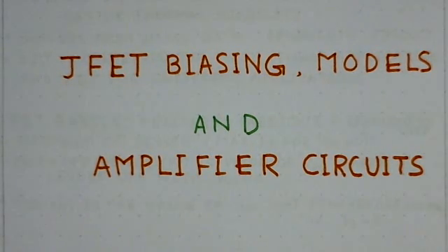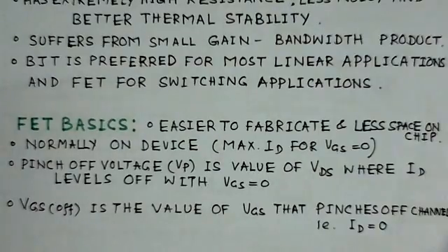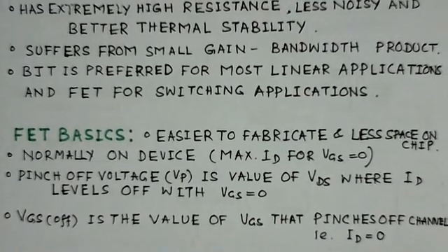A table gives various parameters for common source, common drain, and common gate configurations. Typical parameter values are compared for FETs and BJTs. BJT common emitter and common base circuits are found to give much higher voltage gain, while junction FET common source and common drain circuits have much higher input resistance. Other functions are similar.